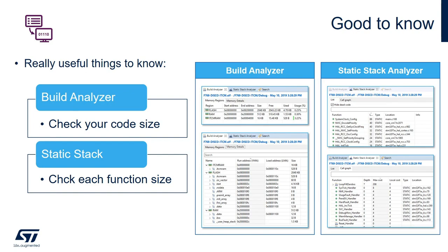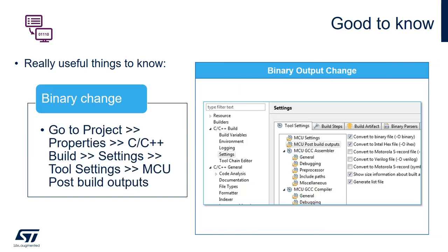And then we have the output for the binary. You guys saw that I was using the .elf file for the debug session, but we can actually choose to have a .bin or .hex, which are more usual and standardized file formats to load your product onto the platform.